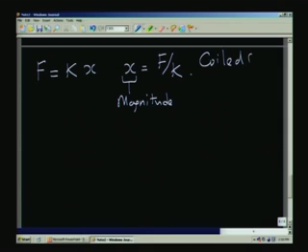What we showed earlier is a coiled spring made of a suitable material, and usually you should not allow the spring to extend too much because it may undergo permanent deformation. So, that is very important. If you subject it to a load which is too large, it may actually undergo a permanent set, and therefore, it becomes a useless instrument. Therefore, one has to remember that there is a certain maximum value of force or weight which you can measure with a particular spring.